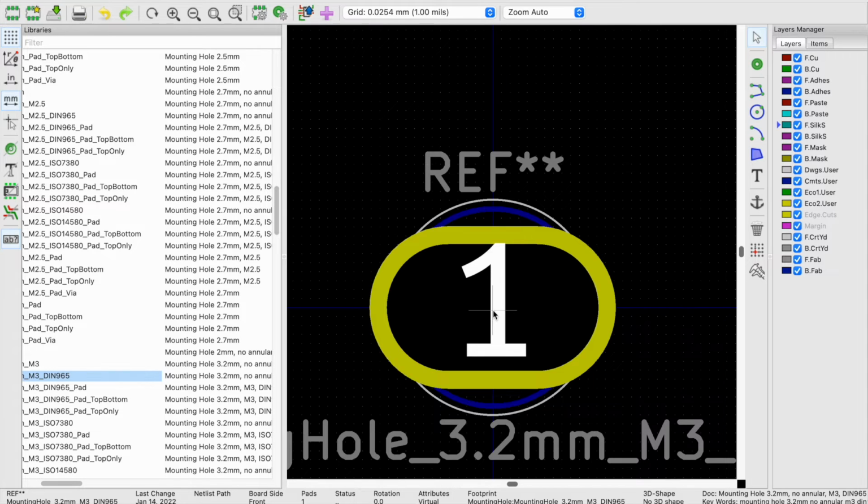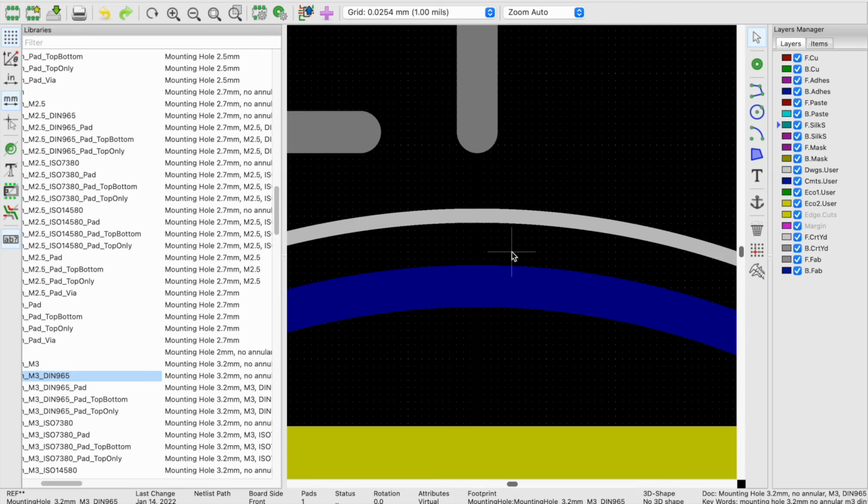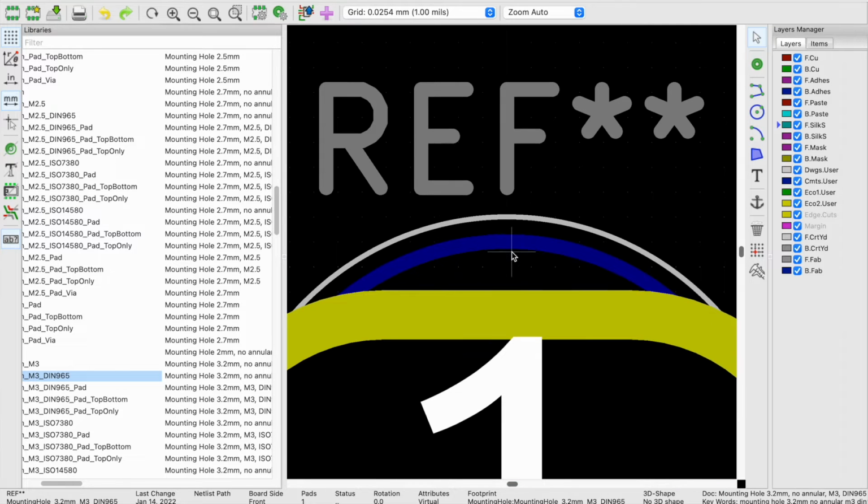So what's the big deal with anchor points, you appropriately ask? Setting an anchor point is telling Kicad where the 0 point is for that particular component. The 0 point essentially represents the origin point of your component. So if you need the center of a component, for example a drill hole, to be 7.5 millimeters to the right and 3 millimeters down from the edge of your panel, Kicad needs to know where it's measuring from. And this from is the anchor point.